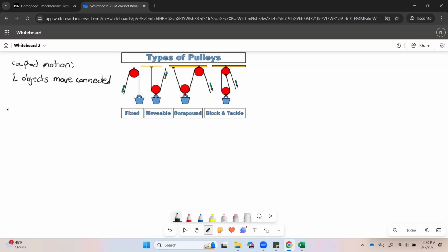We talked about this a little bit last time with like the parent pushing the baby in the stroller or the dog pulling a person on a skateboard, or a little bit with the wakeboarding. The most common aspect of this is pulleys, or application, I should say. So with a pulley, you can give yourself a mechanical advantage by reducing the force that you need to pull something compared to the amount that that thing weighs. But you do this at the sacrifice of speed. So if you add pulleys to a system, yes, it will reduce the force, but then it will have to increase the distance that you pull.